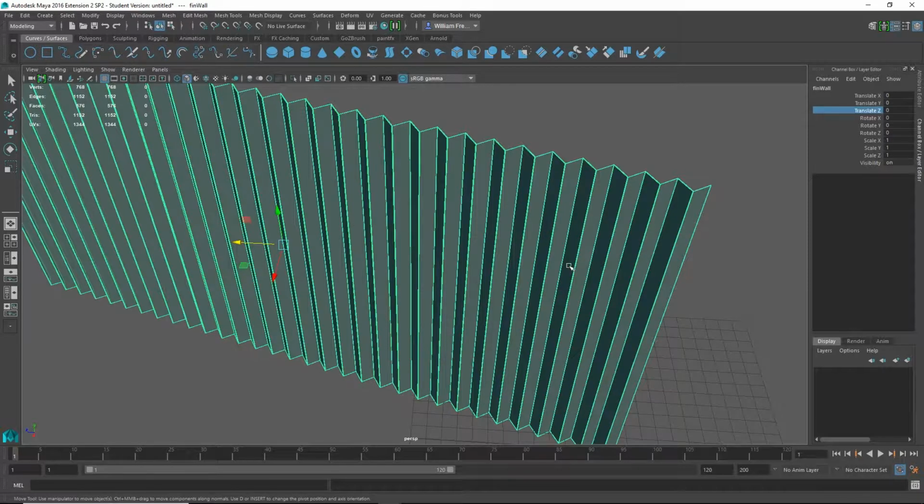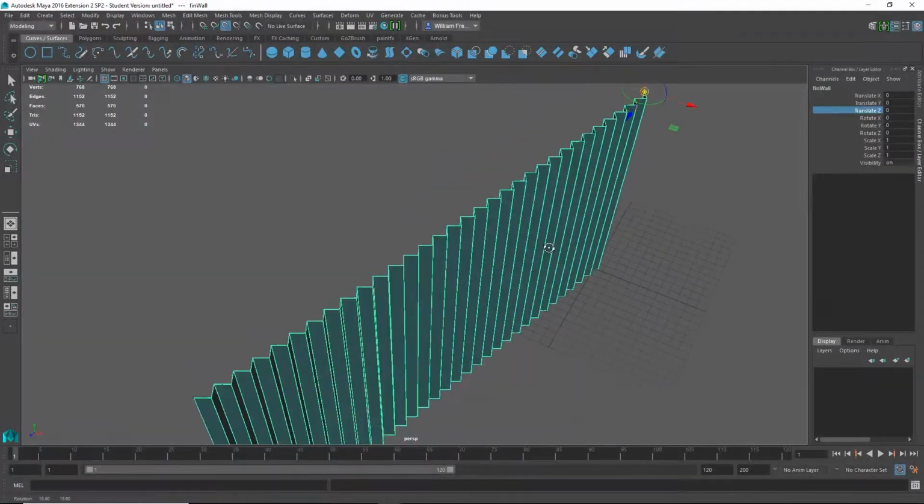I have to select the entire group, and then you hit Insert on your keyboard. So you have to have a full keyboard. Hit Insert, and you'll notice that my widget for the pivot changes here. If I set up here under the live object tools, I can make it snap to grid, snap to line or edge, snap to point, snap to projected center, and snap to view planes, and then I can make an entire object live and just snap it to the surface of that. I want to snap it to the point, and I want to put it up here, not on this one actually, I want to put it on this corner over here.